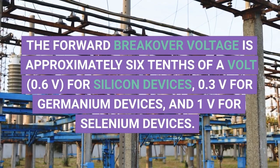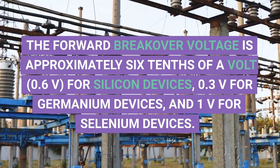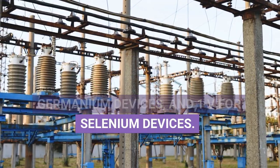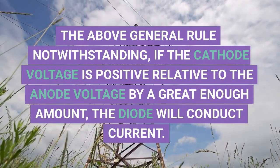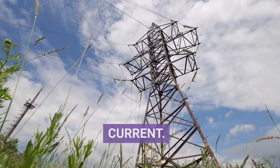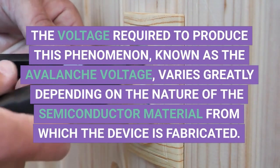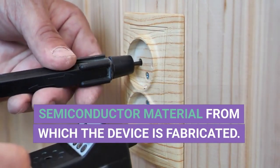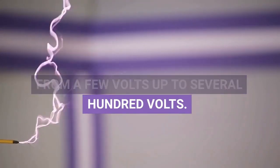The forward breakover voltage is approximately 0.6 volts for silicon devices, 0.3 volts for germanium devices, and 1 volt for selenium devices. The above general rule notwithstanding, if the cathode voltage is positive relative to the anode voltage by a great enough amount, the diode will conduct current. The voltage required to produce this phenomenon, known as the avalanche voltage, varies greatly depending on the nature of the semiconductor material from which the device is fabricated. The avalanche voltage can range from a few volts up to several hundred volts.